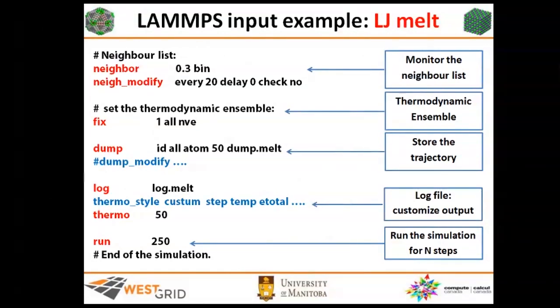If I don't specify the format, there is the thermo_style. By default, LAMMPS prints 5 or 6 different thermodynamic properties. But if you want to change this, because it depends on your simulation, for example, if you are running a simulation at constant volume, you don't need to have the volume in the output because it's fixed from the beginning to the end.